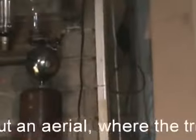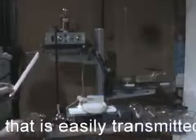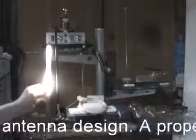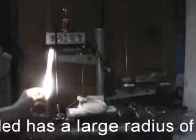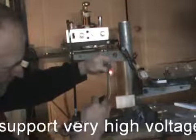This demonstrates the difference. So to illuminate low pressure lamps with the low energy transmitter used in the previous experiments, we have to ionize the pathway with a spark, and voila, it also now illuminates low pressure lamps such as neon indicator lamps, a neon spherical.